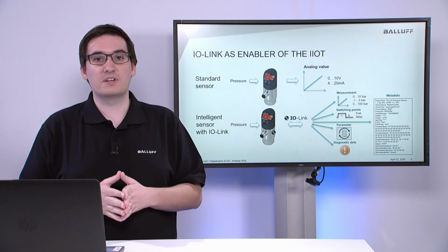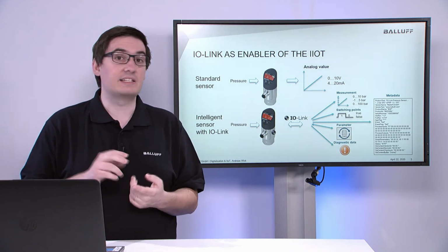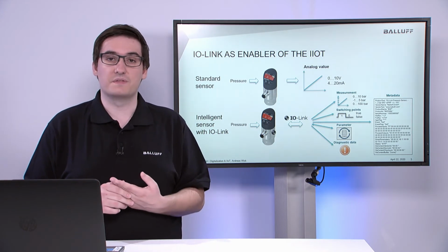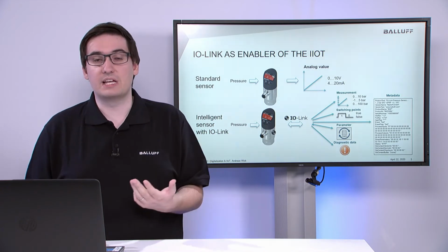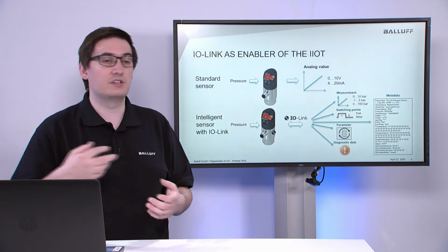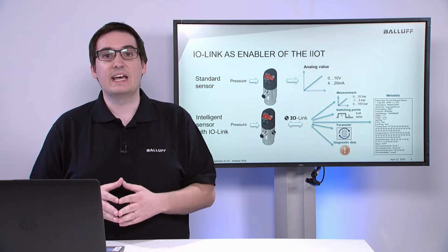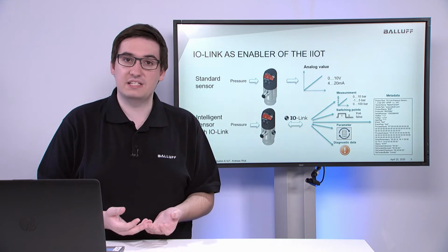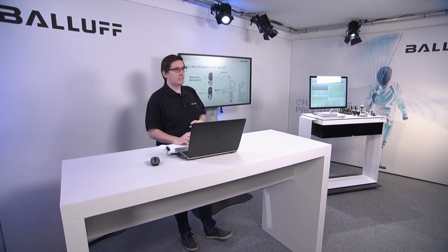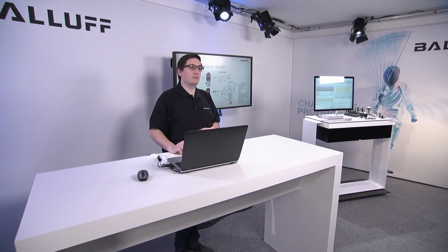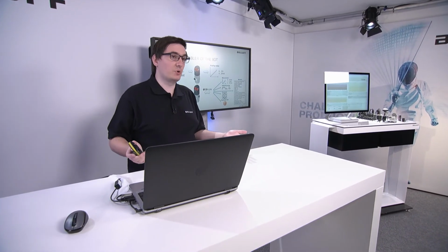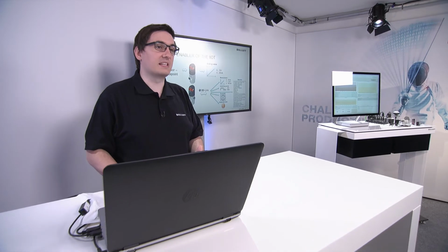Same goes for sensors and sensor metadata, like device identification data, firmware versions of the sensor, hardware versions of the sensor. So you can, for example, build up asset management systems that are telling you whether you have plugged in the correct sensor at the correct machine, and you don't have to program this in a PLC. You can do this in IT applications. And of course, the general benefit: one sensor, one data point with a standard sensor, and one sensor and many data points with, for example, an IO-Link sensor.